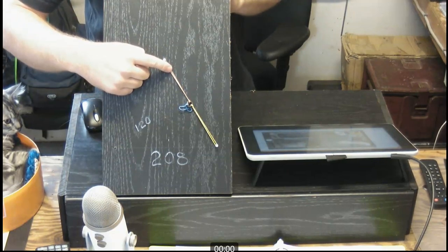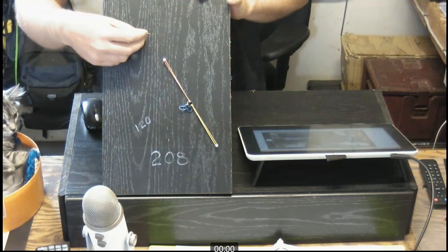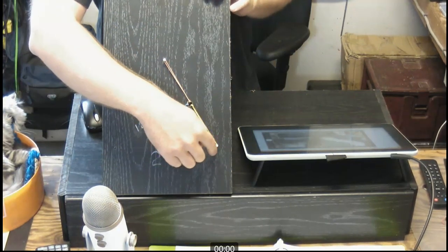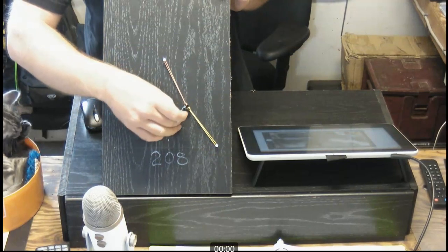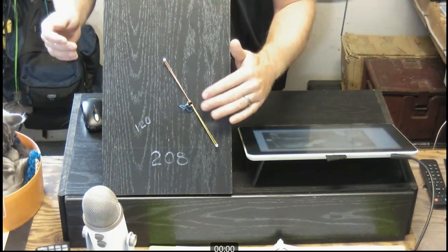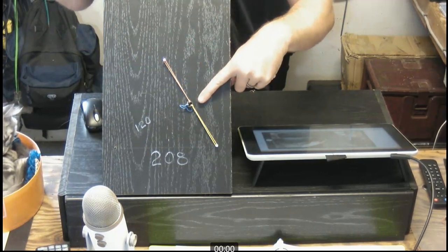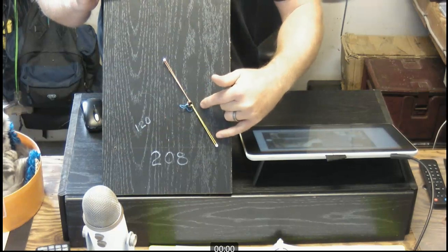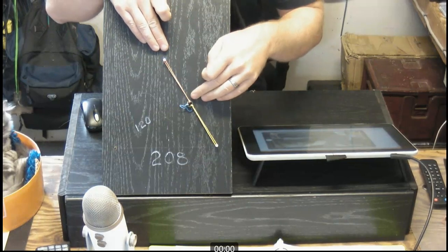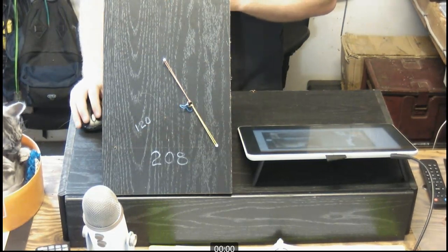And I see that line A and line B snap directly across from line to line. Well, what's this line to line value? This line to line value is 208 volts. But now because I've got this Y connection where all 3 were connected in the middle and I lost that line C, these 2 loads are going to center themselves over top of 208 volts. And because they're equal values of resistance, I'm going to be dropping 2 equal values of voltage. If this is 208 from here to here, halfway down would be 104 volts. Let's compare that with what it shows inside of our book.